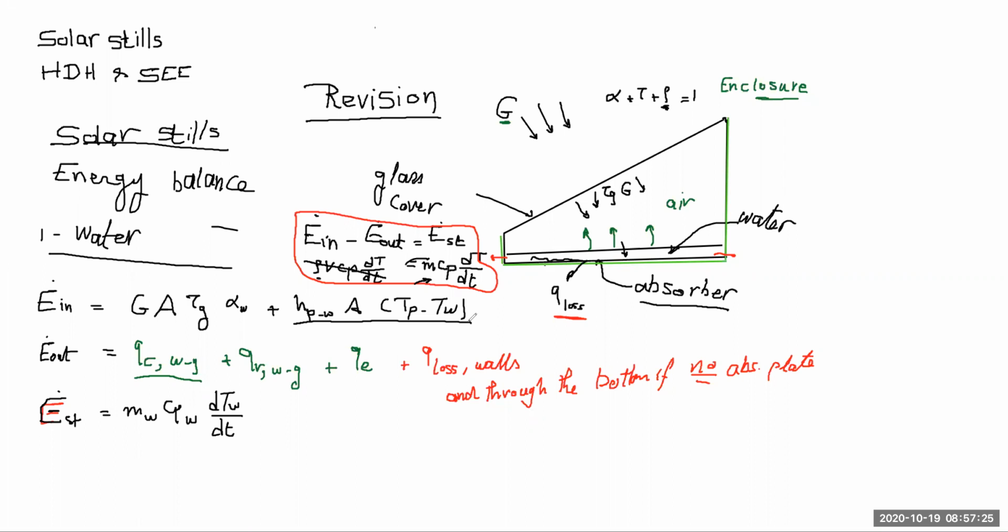How will it boil? Because it is receiving energy. It is not connected directly to the fire, but the water is inside the container. So the container walls are going to be heated first and then heat will transfer to the water inside. How will it transfer to the water inside? Basically, it's conduction and convection. Conduction is too small compared to convection, or if you are going to come up with the definition of convection, it is conduction between the fluid particles and advection. So this is what happens, and it's natural convection because water is not moving.